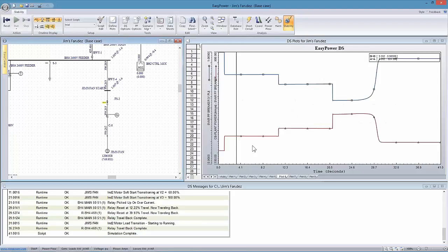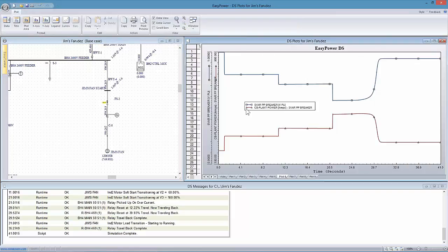All right, so what I'm looking at here again is the voltage and the current at the main panel or main plant input. You can see I come up in stages. So now I'm starting at my 197 and I go to 300 and then to 357 and still up to 457, but that period lasts for, looks like about 7 or 8 seconds at the max. So I've limited my liability, but there's still some sensitivity.